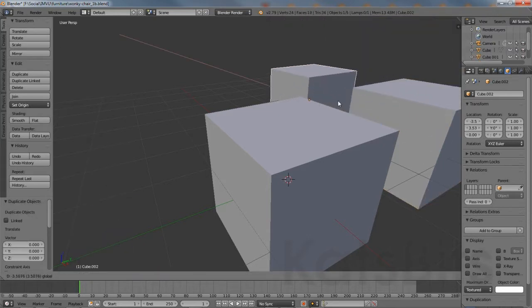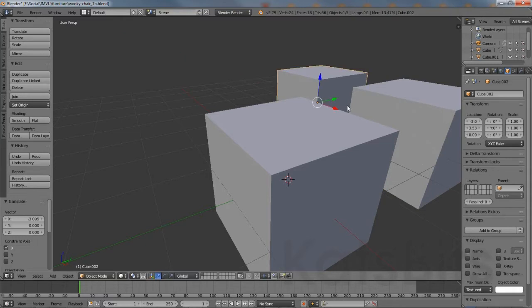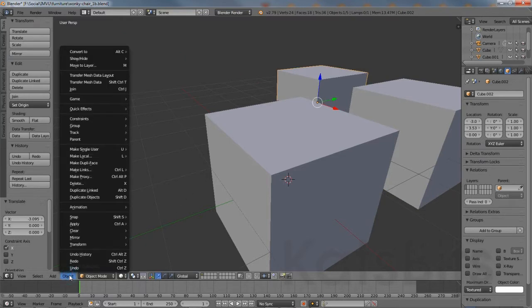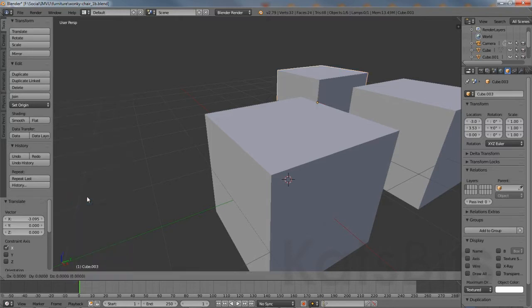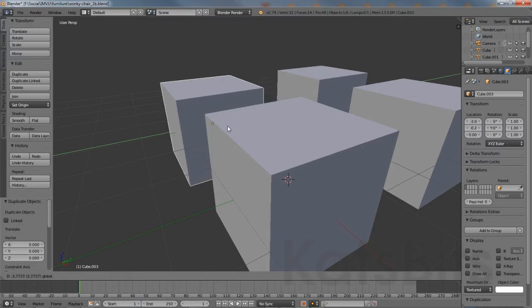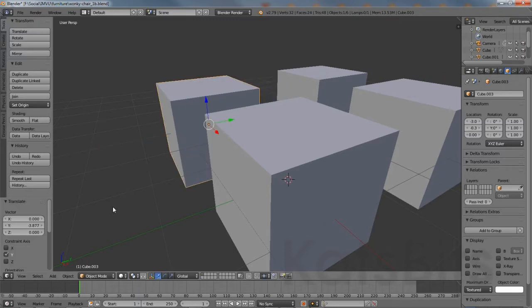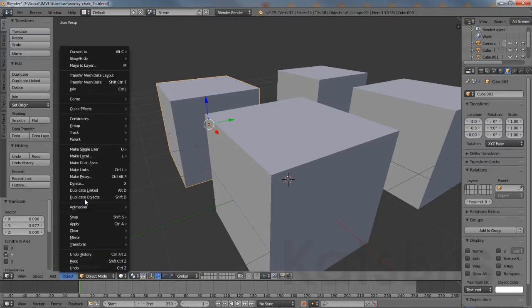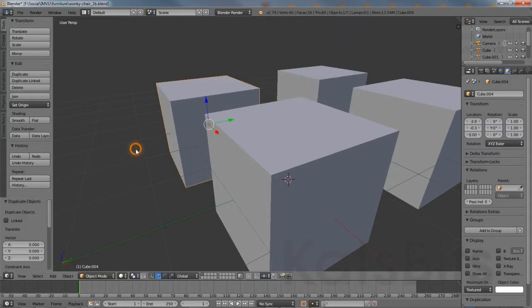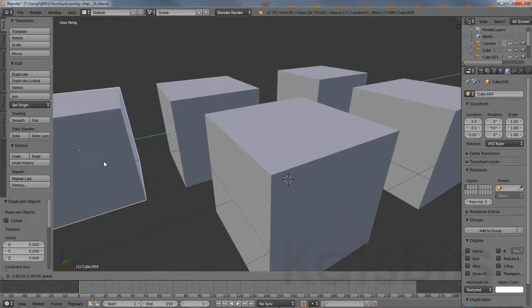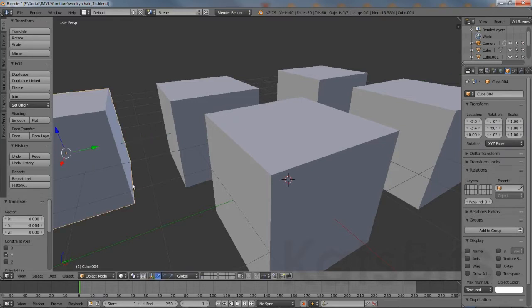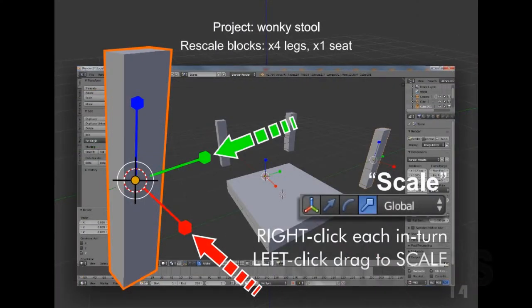Repeat the process using the new object, the active selection by default after creation. With the new object active, right-click if not, that's left-click the Object menu, left-click Duplicate Objects, then right-click to release, so the item can then be positioned left-click dragging the coloured axis handles of the widget. Repeat until there are 4 new boxes, 5 including the original. Once the blocks are available, they can be shaped to fit their role.